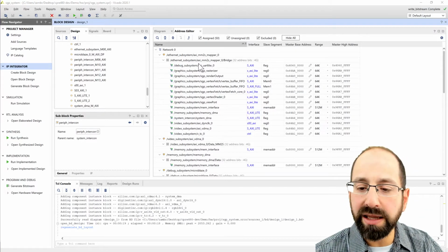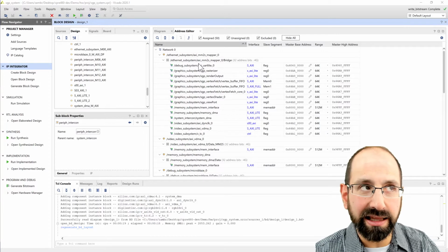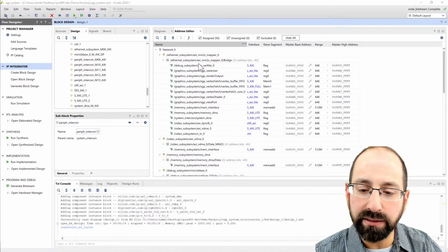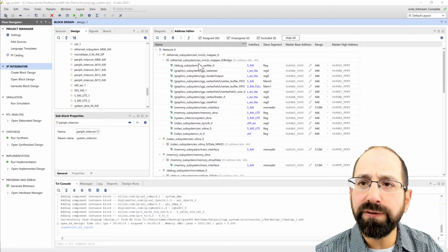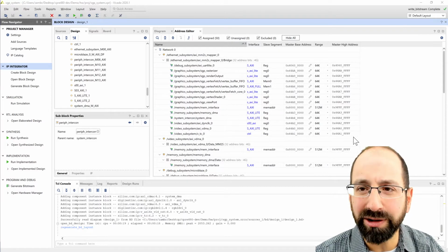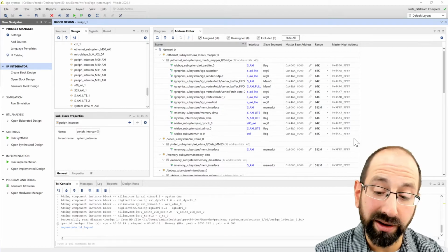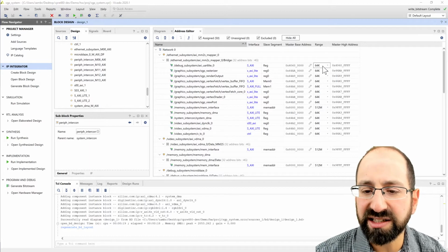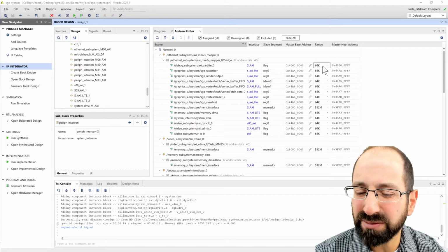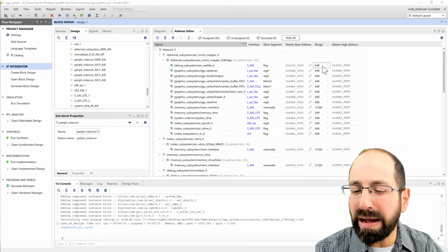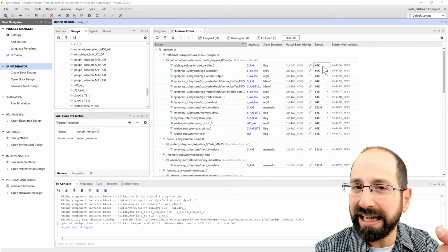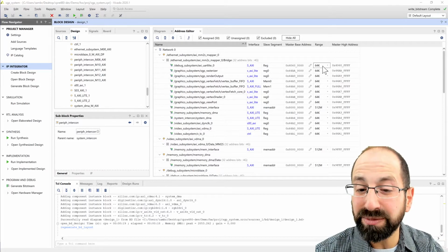We create a UDP IP packet. As part of that, we're setting the AXI write or AXI read address. This interconnect is then looking up that address in what effectively gets generated as a really big table here and determining which slave port that physically would correspond to. You're seeing memory regions of the range of 64K as a minimum here. We can make it smaller. You keep it a power of 2 anyway because that makes the actual decode logic as simple as looking at just an individual bit of the address that comes in.